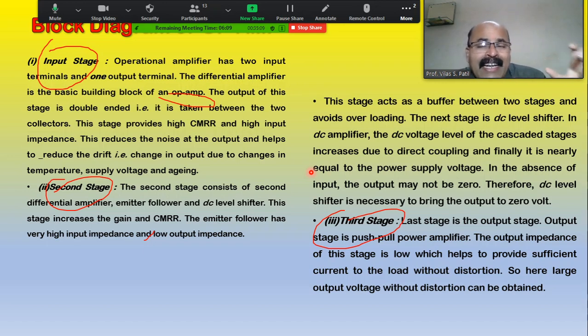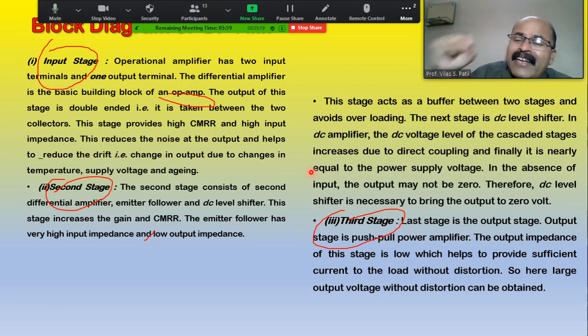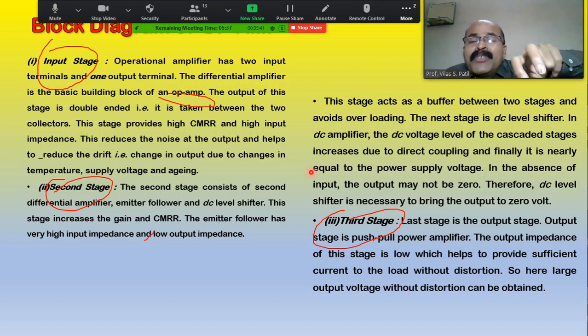When we use the null detector or the null shifter pot to calibrate the output of the operational amplifier, it regulates the DC level shifter, and the role of the DC level shifter becomes active at this stage. The level shifter can shift the output of the operational amplifier in either the up direction or the down direction, and by moving the pot with a screwdriver easily, it is a mechanical treatment.